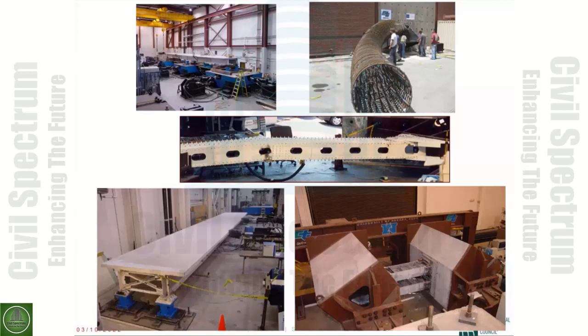So they tend to have rebar cages standing up, with guy wires for these. Recently, because of construction methods and means, we started to see failures and, unfortunately, deaths when you have a failure like this. So we started to investigate the behavior of these cages and how to prevent them from collapsing during construction.